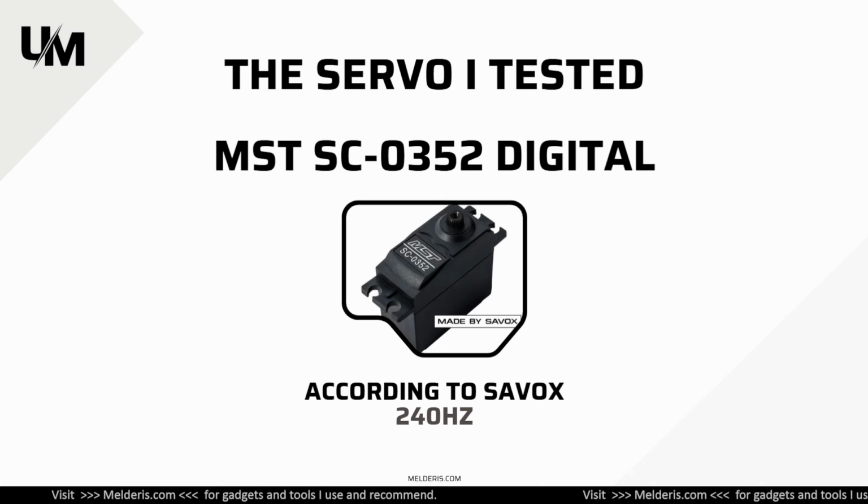So if you are looking for a servo, pay attention to this number because this is important. What I can tell you right away is that these days, those are the standards: 50 Hz for analog systems, 333 Hz for digital. Most of the digital gyros these days will be using 333 Hz, okay? That's something which comes down to the manufacturers of gyros and servos. They do not provide this important information, and that is why many people are making mistakes, because you simply cannot find what type of frequency they are using. And as you can see, it's very important.